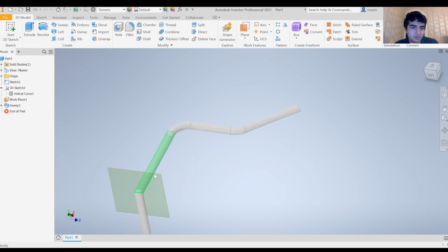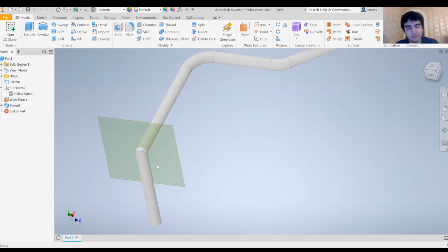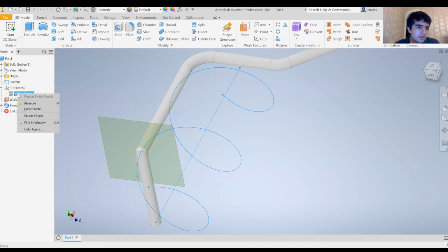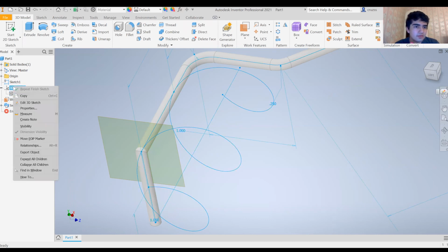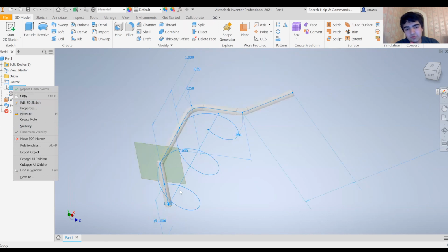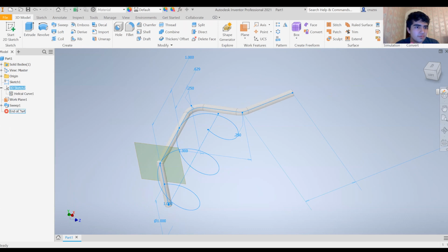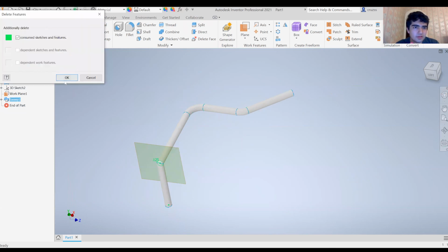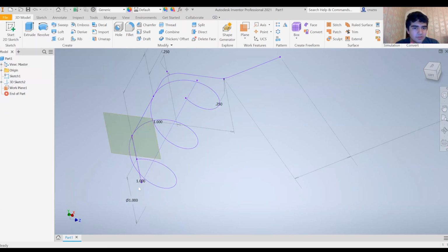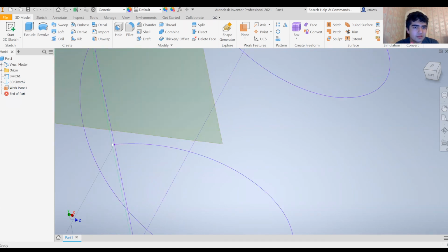Awesome, perfect. So after you're done making cool 3D macaroni, you could probably expect that I could also do this for this helical curve here. So let's say I get rid of this nice crazy macaroni. Let's go ahead and undo this application of my sweep. Get rid of that sweep. Now what I can do is go back into the sketch, click here, and as you would probably expect, I can create a plane.